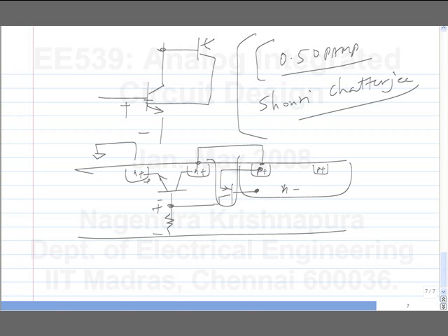Okay, the point of making a half volt op-amp is, let's say you have half volt digital technology. The fact that you can make any analog circuit at all in half volt is a big deal. Okay, it's not that it's necessarily better; it may be worse. In fact, it's been shown that if you want the same functionality with the same specification, that is the same SNR, in a high voltage technology and a low voltage technology, in a low voltage technology, you may end up burning more power.